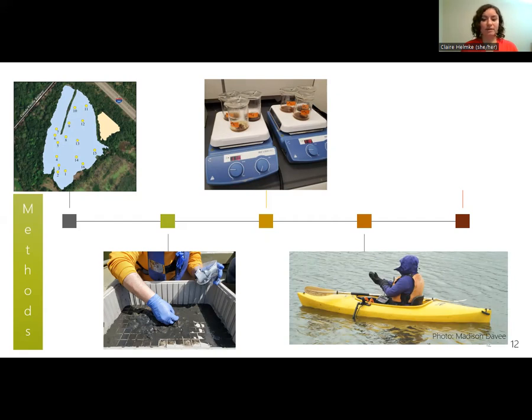On the same day, 2 of my lab mates surveyed the depths from each sample location from a canoe using a survey rod. This was especially important because I ran aground trying to get sonar to that section of the lake west of the peninsula and couldn't continue mapping in that direction, but the canoe could. We utilized CMAP's EcoSound to convert the sonar files into bathymetry shape files using a kriging interpolation.